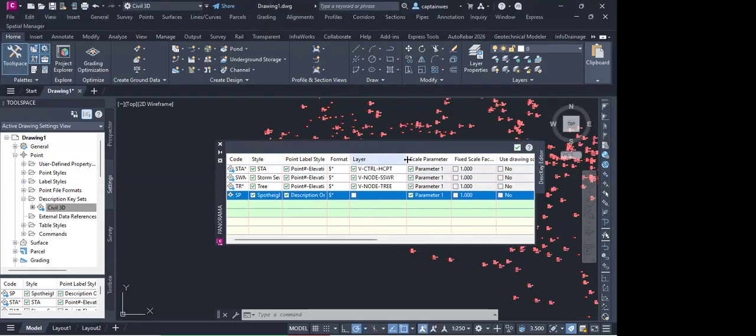Remember, I don't know if I said this as we started, but I think I should have, or Engineer Brescia should have said, most of the layers that are already preset in the software, probably they'll be used somewhere. And you don't want a scenario where when you're working on your drawing and you freeze an element, it freezes something else that you are working on. Or when you modify a certain layer, you find you're modifying a certain element that you had not planned for, envisioned for it to be modified.